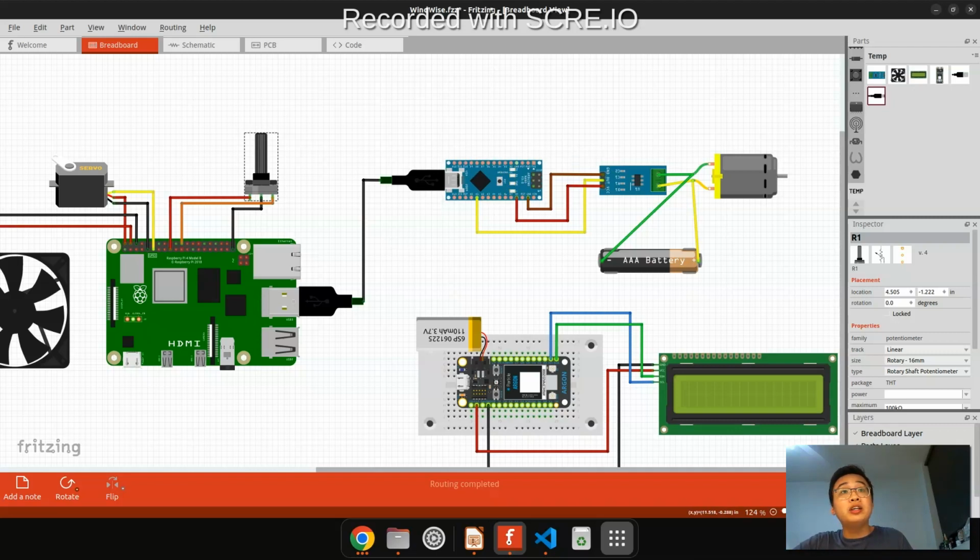The Nano here basically uses a current sensor to read how much current the windmill is currently producing, to see whether it is effective, and also to plot a diagram of the current flow in the windmill. So again, all this Arduino Nano is doing is using a current sensor to read data that is generated from the windmill, coming from the DC motor.